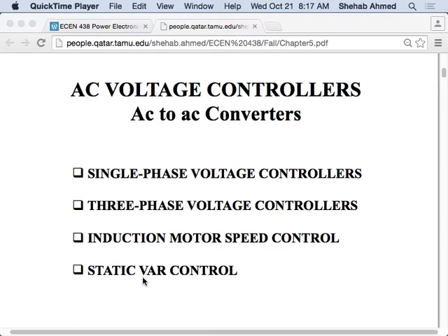Again, the generator will provide a certain amount of apparent power, so active and reactive power. If the power factor is lagging significantly, then you're providing a lot of reactive power, which means you're limiting the amount of active power. So it's apparent power that's important. If you're not being paid for that reactive power, then you're not going to be able to compensate your investment because you're not generating enough real power.